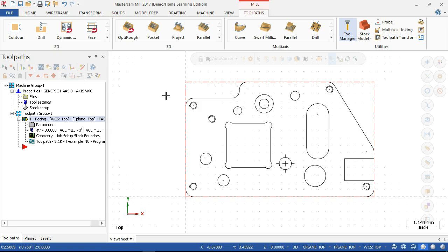Right? So the last couple pieces that I ran that had to be flat, I haven't measured, but when I put them down on the surface plate, I got that little bit of air suction that told me they were pretty darn flat. I had 10 foot-pounds on the vise. And I did not push anything harder than about 20 inches a minute. And it left a nice, pretty finish. I think I pulled up the picture video off of my cell phone, and it had that nice pattern mirror, but it took a little bit longer than just plowing through it.